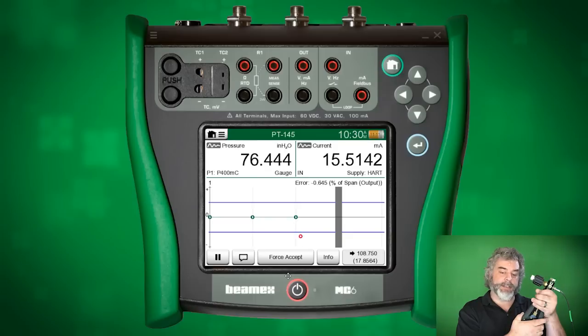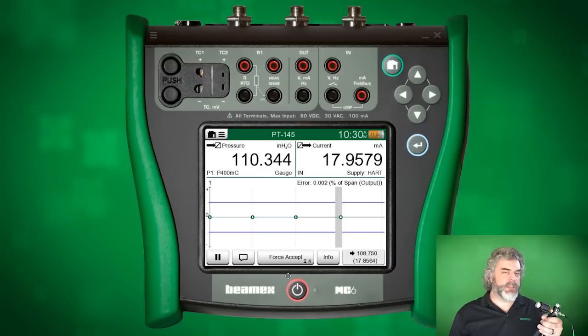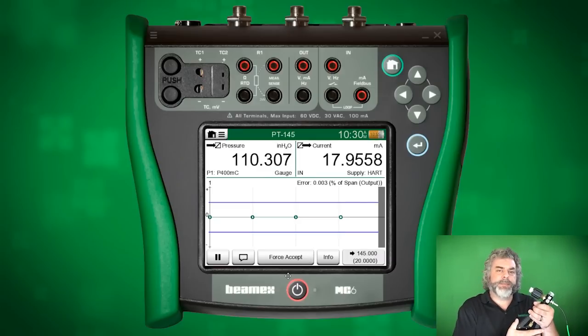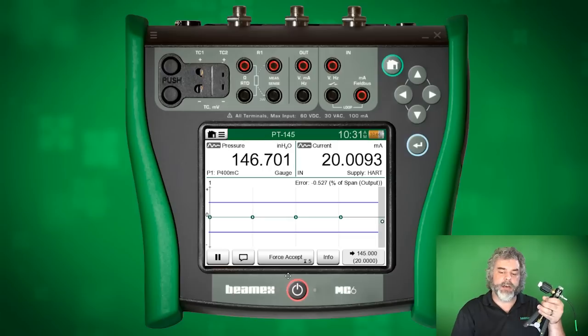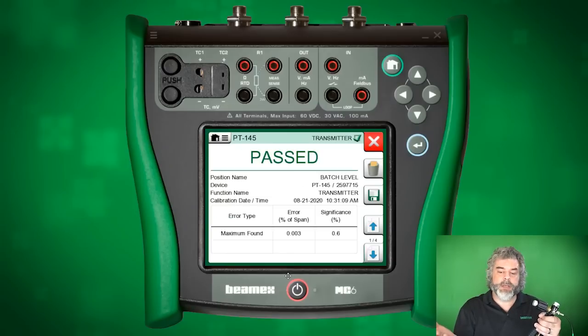So we don't have to get it exact. And this is one of those things that don't do more than you have to. Even the number of test points. Do you need to do an up down or a 5 up down? And in some you might, but a 5 up down test in many cases came from pneumatic instruments, and they had horrible hysteresis. In fact, on some pneumatic, you would have it okay on the 0, 50, and 100, but then the 25 and 75 would be off. So that's why we had to do 5 up.